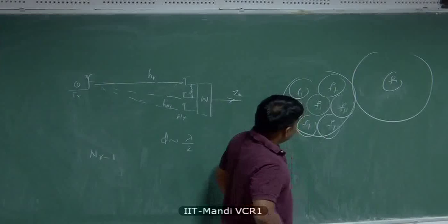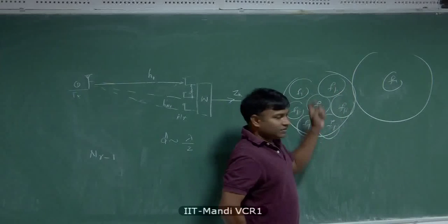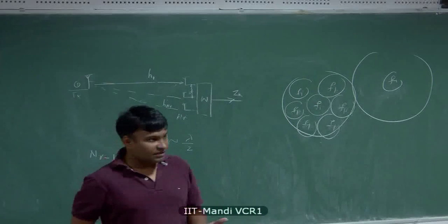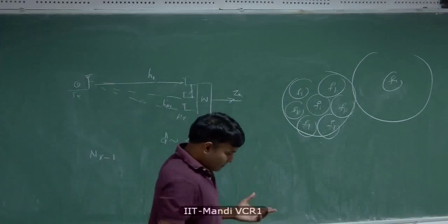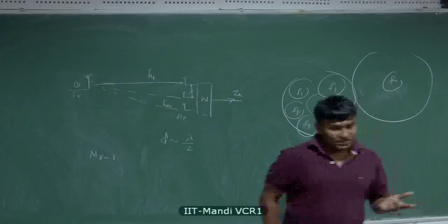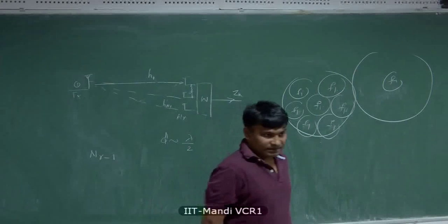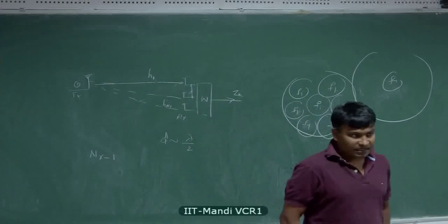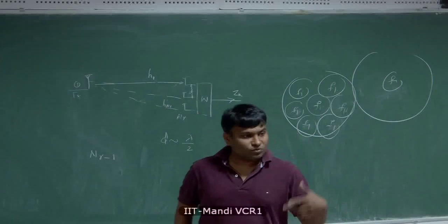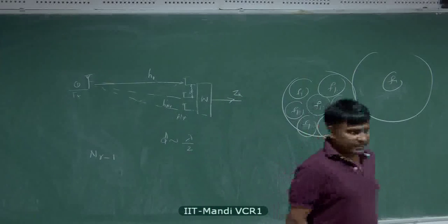Then you may argue that, if you are close to the base station, anyway the interference levels are low, although there are a lot of interferers contributing, and you can live with it. For systems that use data transmission, not voice, a signal to noise plus interference ratio of even 0 dB is acceptable sometimes, because if it's a broadband system, you'll just use more bandwidth to get a given data rate.